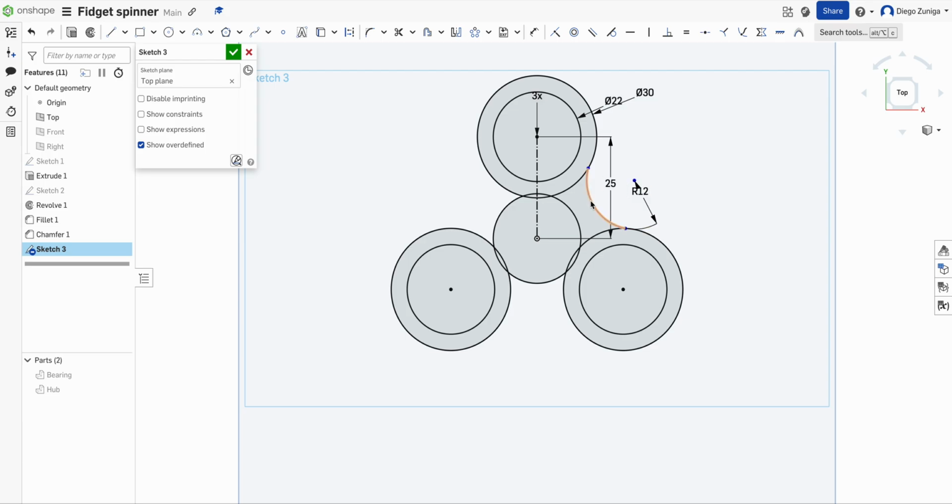But you can tell that this line and its points are still blue, and we're going to define that this point will find its right spot when this curve and this circle are tangent. That's where they barely touch, they barely coincide. So by using the tangent constraint, I'm going to select this curvature and then this circle, and because I haven't deselected the tool, I'm going to do the same for the other circle, this and this.